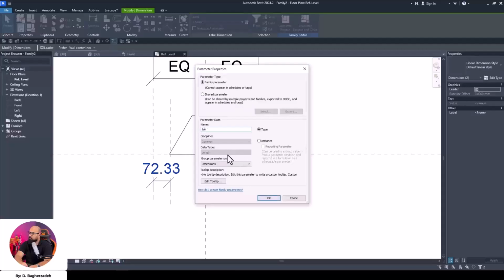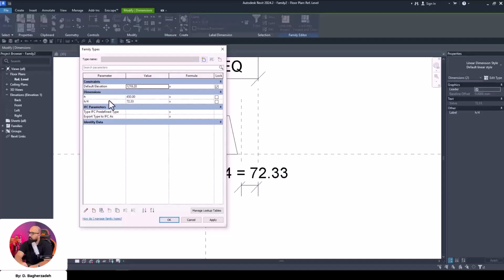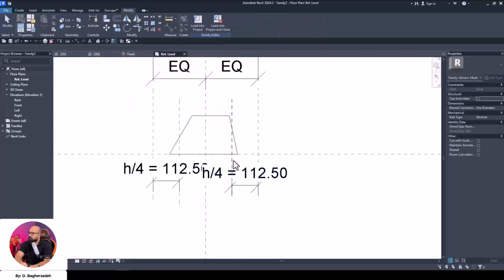Not going to use the division symbol, because if we do so, later on when we are specifying the formula, we should put this inside parentheses. So guys, if you do want to use the division symbol, don't forget the parentheses, otherwise your whole formula would be ruined, because it won't be counted as a name. Alright, okay. Now, for the formula here, it is quite easy. Just divide whatever value we had by 4. Apply, and OK. Alright, moving on.